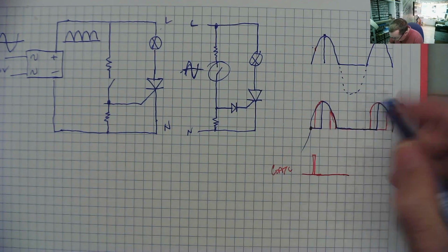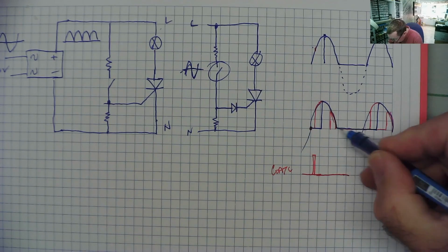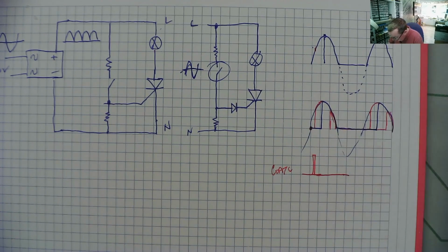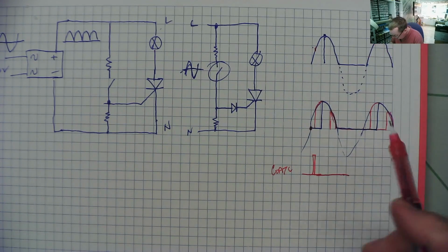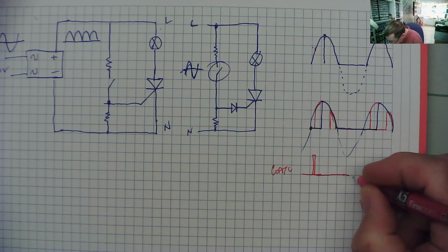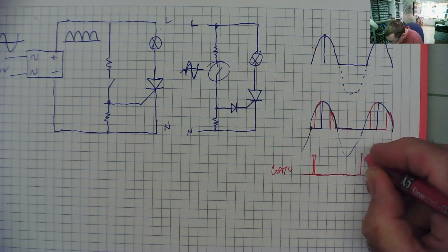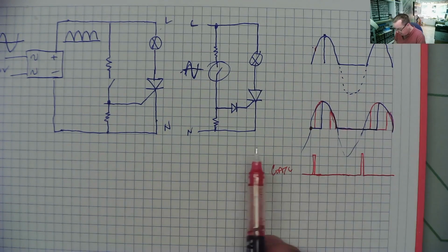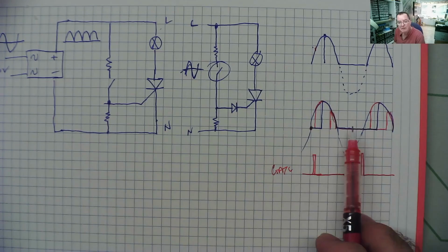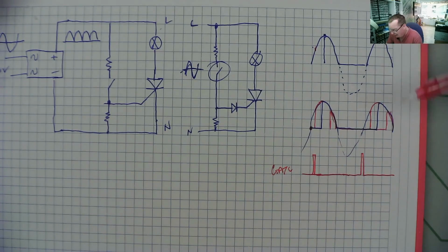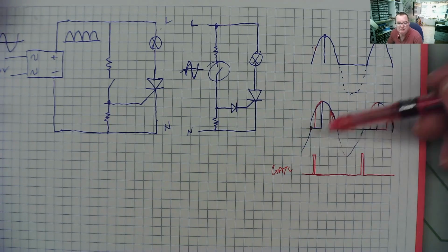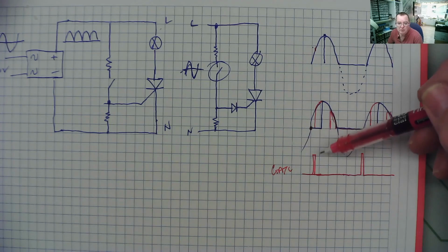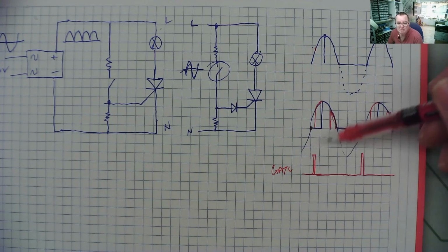As the voltage passes 0 again, so this is the 0 passing point, we can detect that and send another pulse. Very short duration pulse, low voltage, and that's how you control the thyristor. And you can see if you move the pulse up or down, sideways, it's almost like a sort of pulse width modulation, but you're not actually modulating the width of the pulse you send.